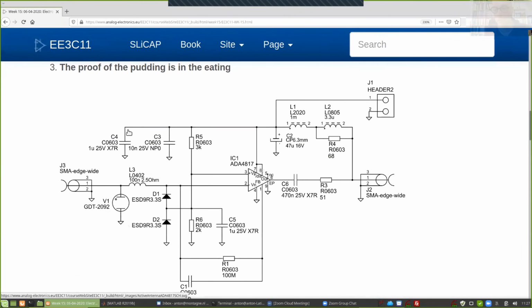Here you see the operational amplifier. Here you see the coupling capacitor at the output. Here you see I did not take half of the power supply voltage. It had to do with the common mode input voltage range of the operational amplifier, but it can be changed. Here you see ESD protection. Here you see there was no phantom zero required. I put a little inductor in it to prevent very high frequency signals coming in. And together with the resistance of the source that I have, it was enough damping, but you can forget about this.